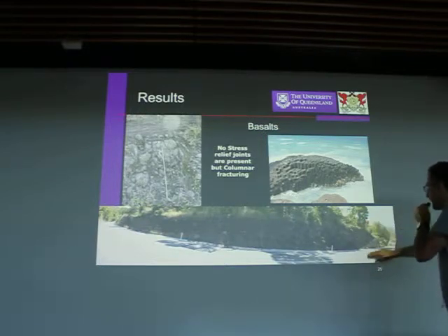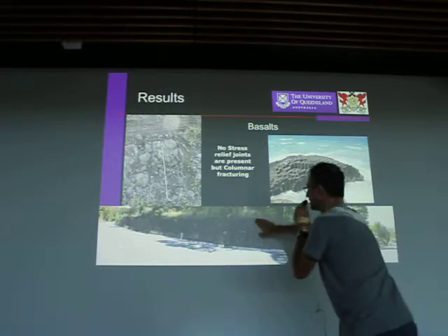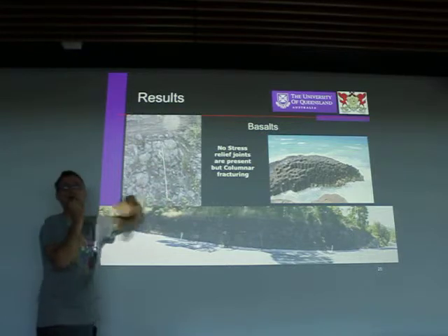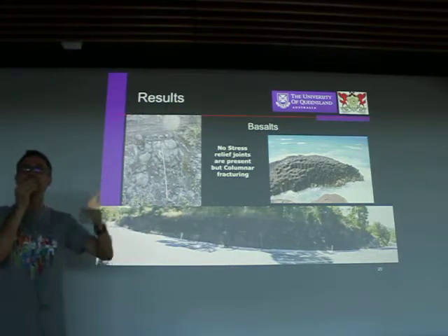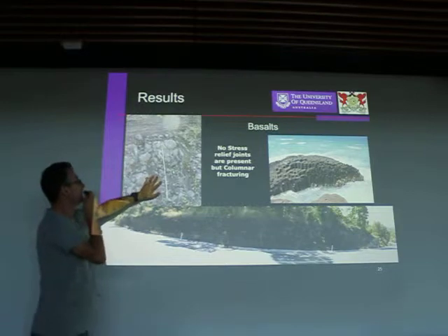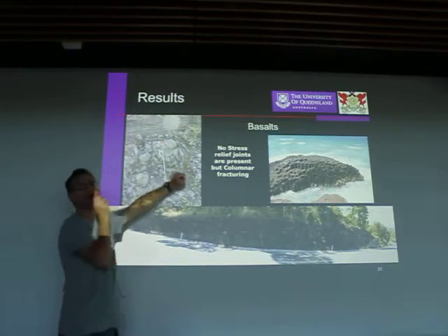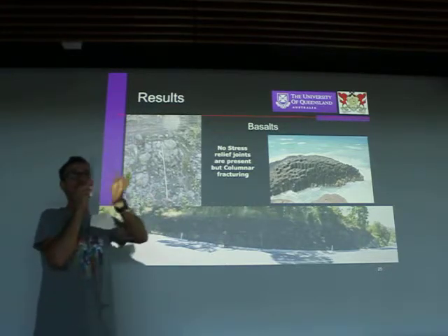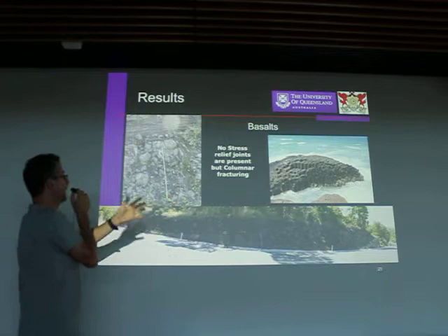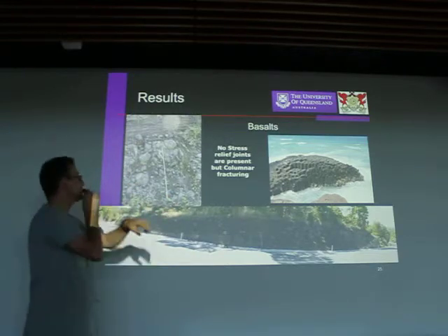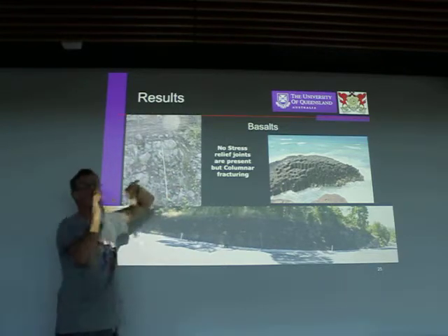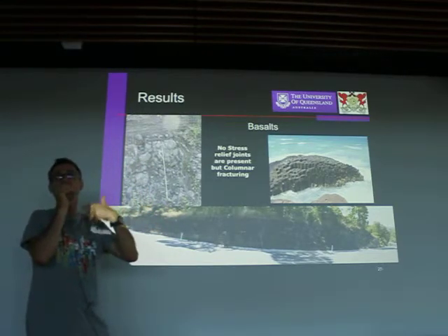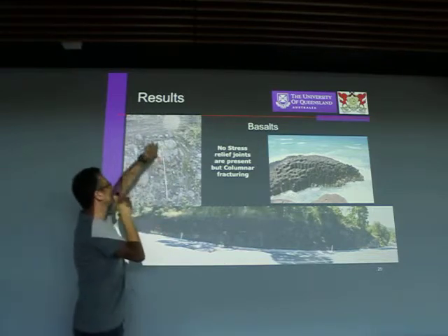This lava flow here comes from here, some rock, here to here, residual soil, and we can see that the most important parameter to identify the different layers that occur within this weathering profile is the soil to rock proportion, because what happens here is that the weathering occurs along the fractures and from outside to inside, leaving some blocks immersed inside the residual soil or a very weathered material that surrounds these rocks.